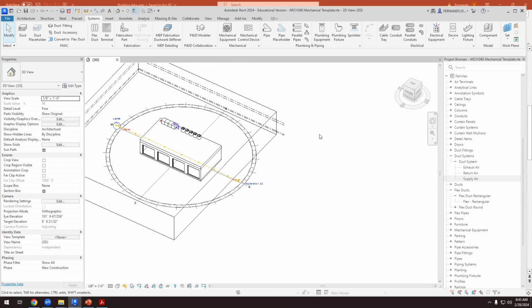So now we have different options. For the PV panels, basically we have two options. In this building, you see that we have a huge PV array, and that PV array is detached from the rest of the building. We have a structure, and then we have the right orientation for all the panels. This is very efficient, and probably they did this because it's the most efficient way to make the most of the solar panels. It's quite expensive because we have to build another structure at the top of the building. We need to build a different structure. There's something that is easier and cheaper, but probably not as efficient.